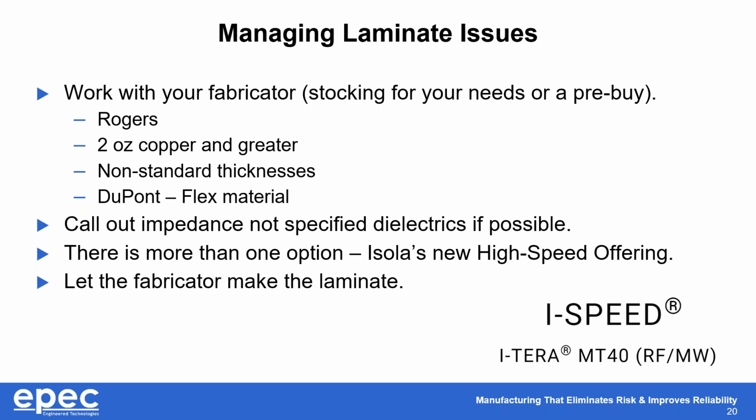Non-standard thicknesses, right? Again, if you're running a non-standard thickness, that could be 2 to 3 to 4 weeks. Anybody who's been working with DuPont's flex material these days knows that it can be up to 12. That's something that we're seeing a lot of.